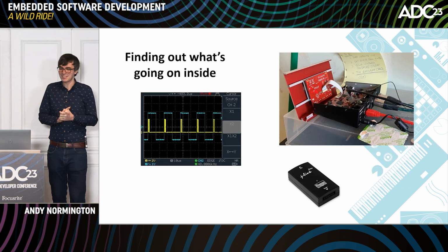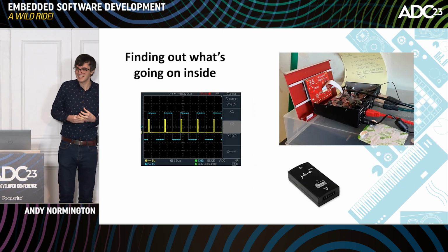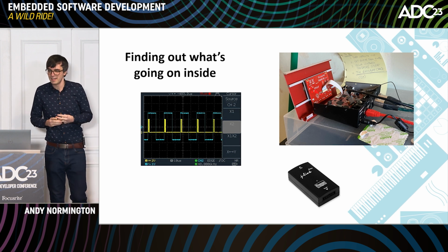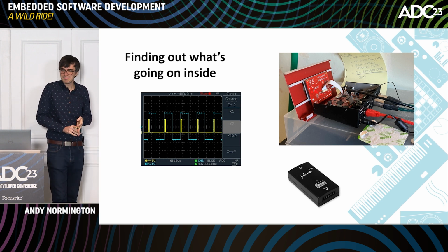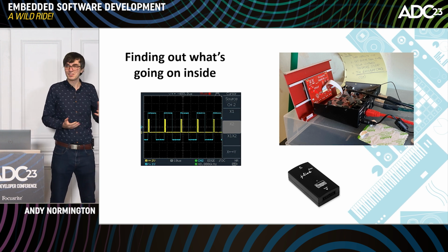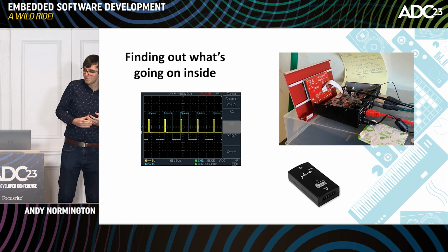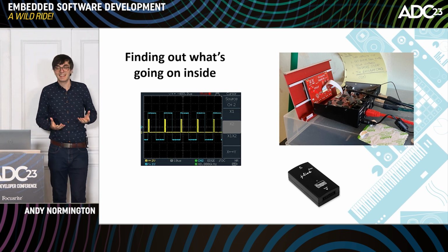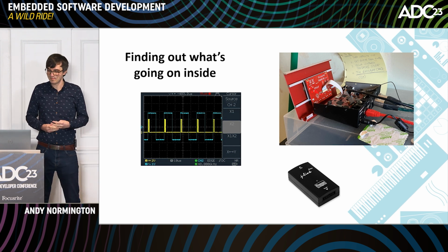The purpose of all these tools is all about getting a window into what's going on in the hardware. So we have debug and trace tools to help us do that. But you can learn a lot from just having a couple of spare pins to toggle at different points in the execution. Maybe we can print to a serial port, and that can be all we need to get us some basic profiling.